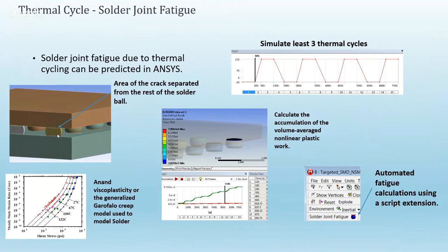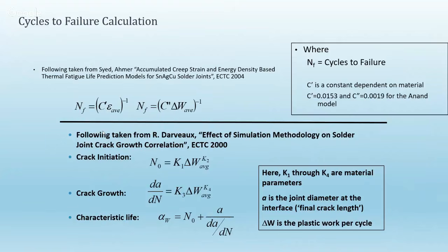And at that scale, if you have an entire PCB with multiple packages and thousands of resistors and capacitors, setting up a simulation to this extent would be very cumbersome. Which is why this is really good for detailed analysis of individual packages, and Sherlock is a great way of scanning the rest of the board to see if there are any other issues you should be worried about.